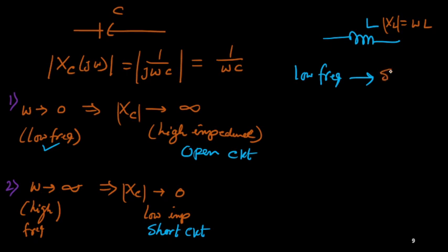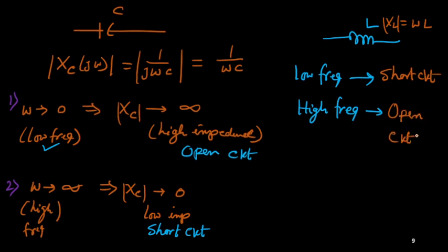It will be considered as short circuit. Whereas for high frequency, this inductor could be considered as open circuit. It's a very, very useful concept.